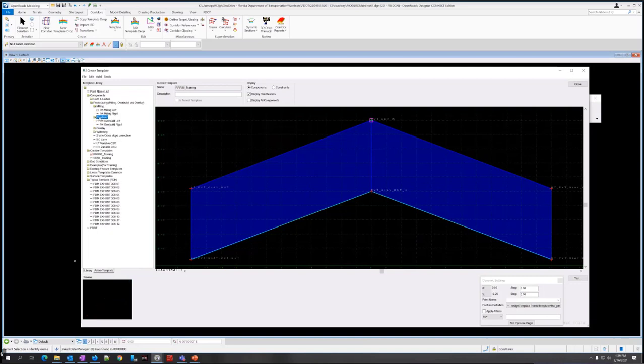So we'll go in here into overbuild, over here in components. And this one is going to snap to the same point, actually. So the pavement overbuild right is going to snap to pavement overlay bottom in here. You can also drag it from here. You don't always have to drag it from the preview.